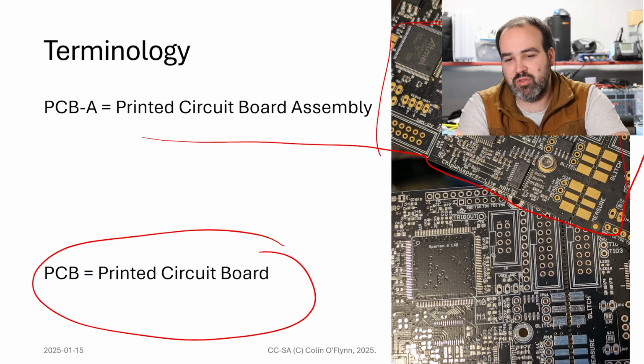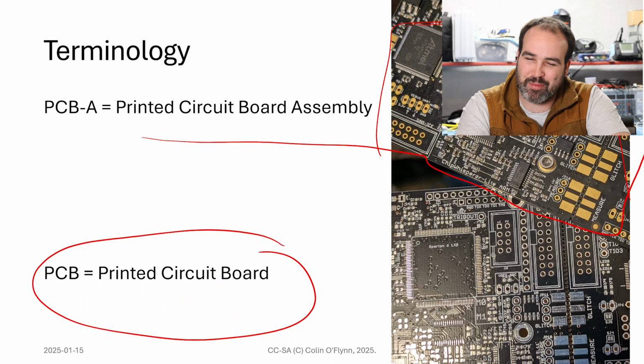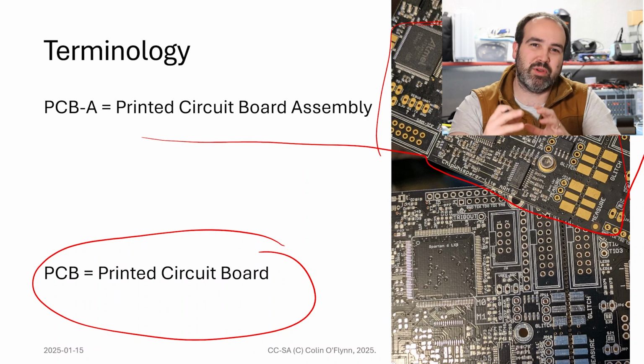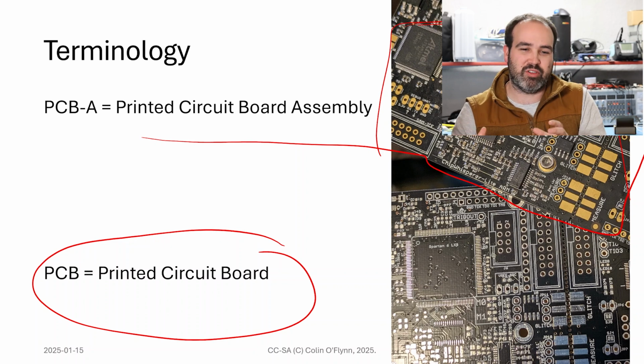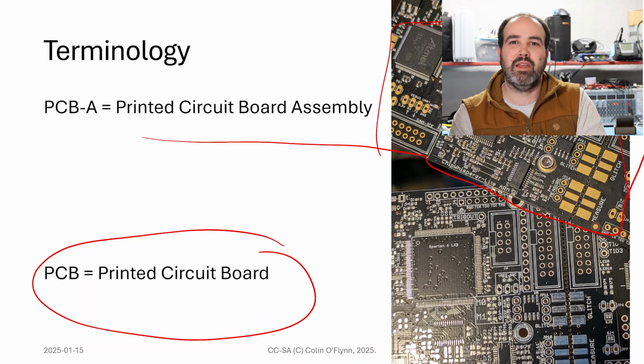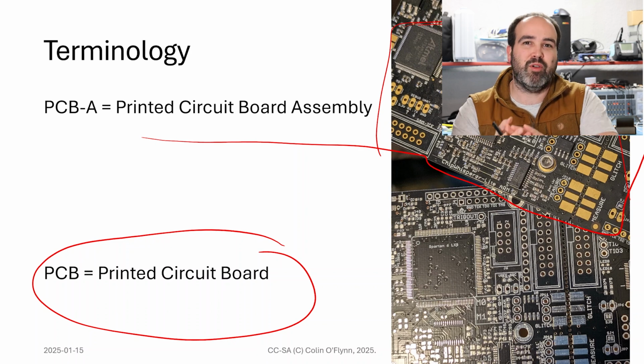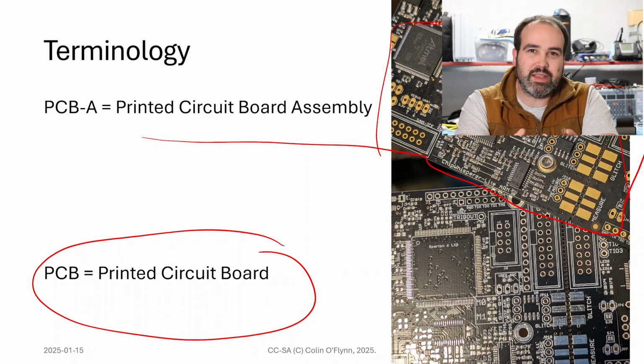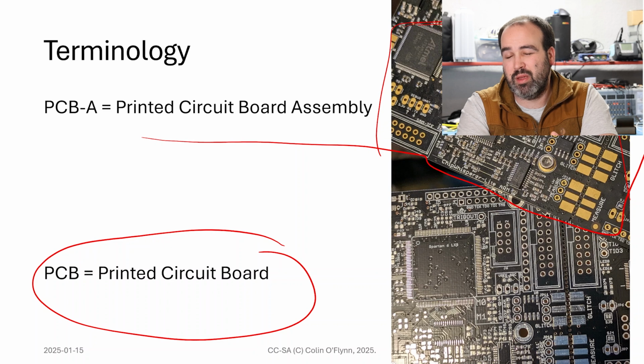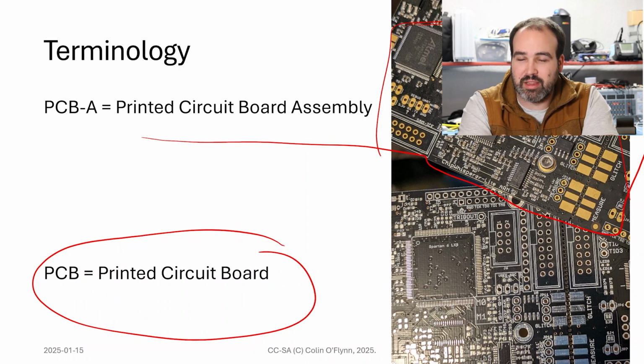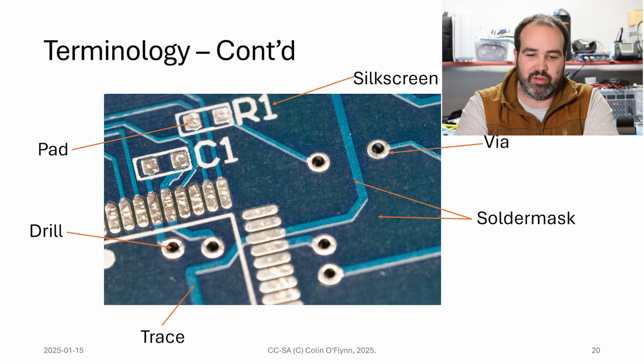If you're not used to soldering surface mount parts, you may like assembly because when you're doing a bring-up of a new board, you're prototyping your design and your assembly, and if you had firmware, your firmware as well. So what you might like is that you don't have to think about whether you've done the assembly correctly. You might prefer that someone else has done the assembly for you, and presumably that soldering has been done to a higher quality than you're going to do.